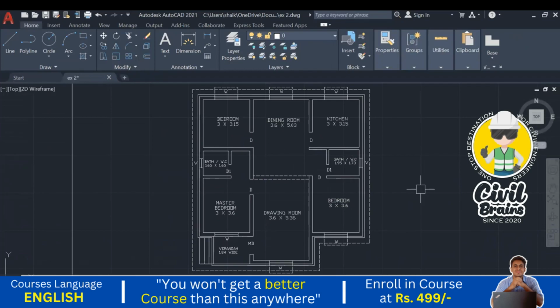We are almost done. So the next step, that is the last step of the plan, is we need to show the hatch. We need to hatch the walls. Once you hatch the wall, then everything is finished. But we are not hatching right now, because once we hatch, sometimes it is difficult to edit some things. Once you go to the elevation, then some difficulty will come in a section also, if modification is required, then it is a little difficult to edit the hatch.